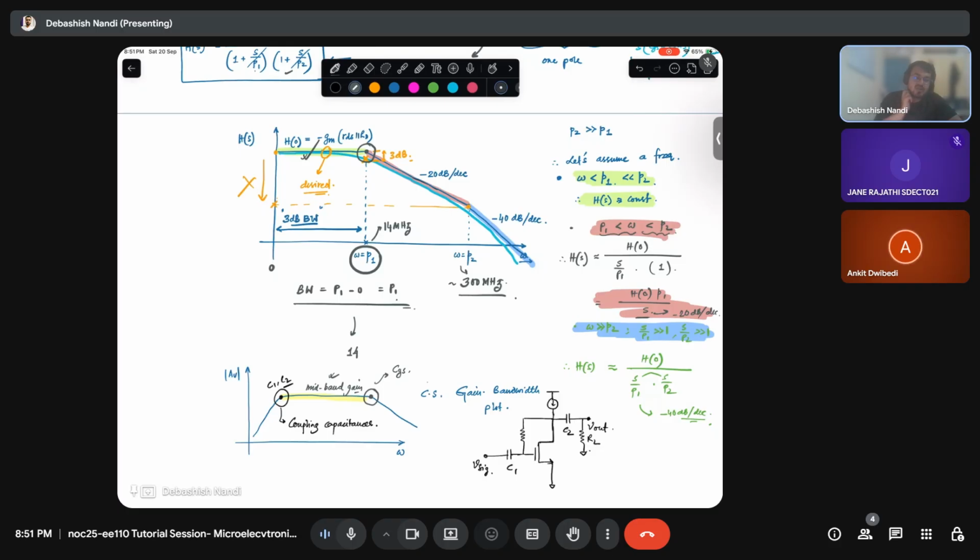And also there is a common term called gain bandwidth. Gain bandwidth product is constant in a common source amplifier. Be very wary of that. That is not always true. It depends on the circuit topology and how you make that. Not all common source amplifiers have a constant gain bandwidth product, and it is not absolutely true for common drain and common gate structures.